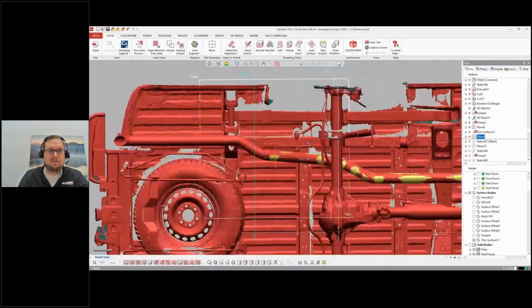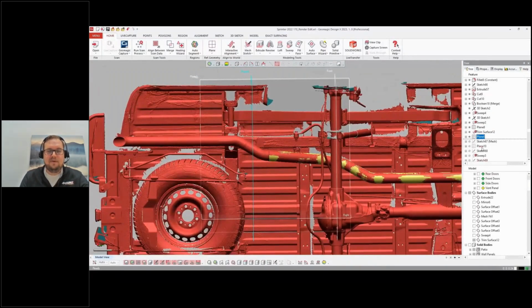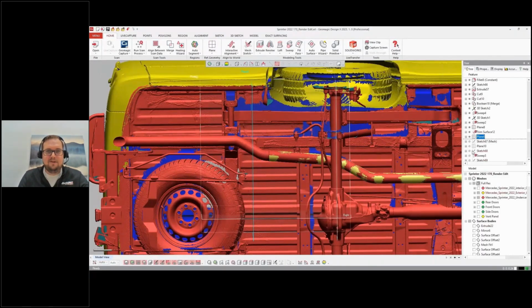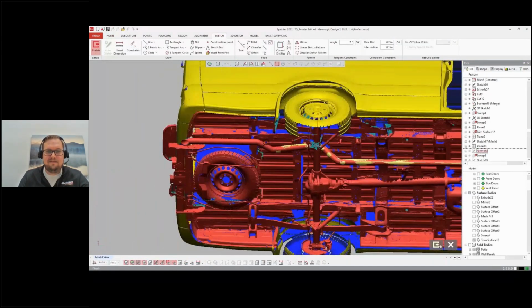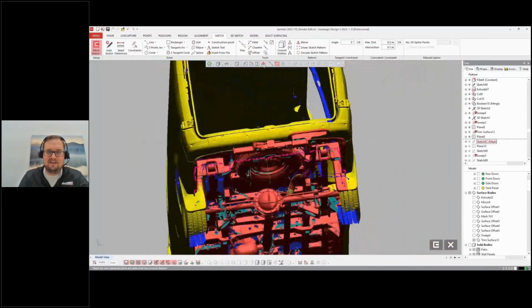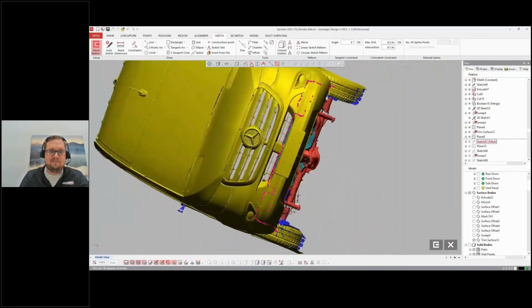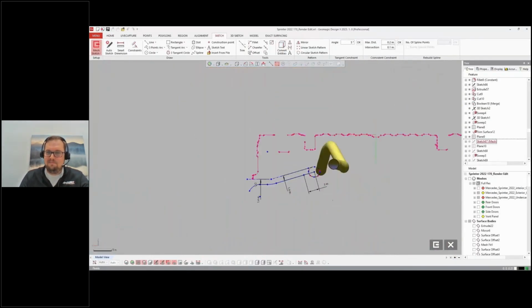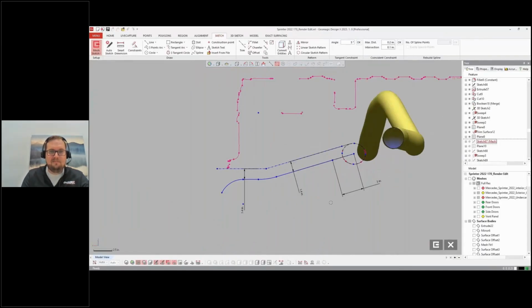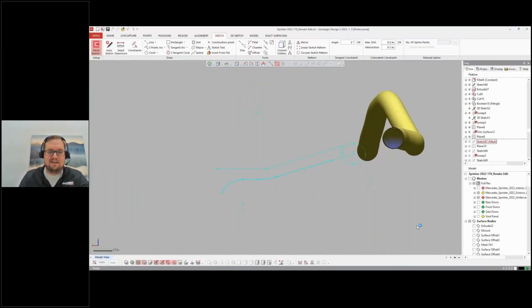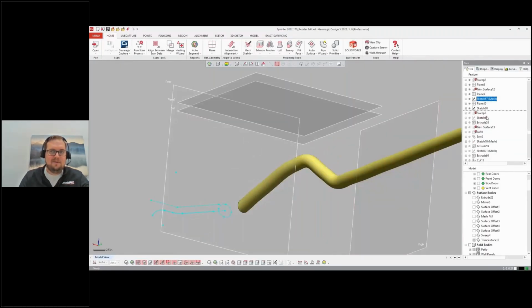And I am going to do a quick sketch on this new plane. And I want this exhaust to exit just after the rear wheel. Now, I did actually look at creating some dragster style exhausts, but I figured that might be a little too high profile. So I'm going to do just a very simple turn down here. So once I have a sweep path and a sketch created for this, I can go ahead and make another CAD surface. So you can see I'm utilizing that mesh sketch to tell me exactly where I need to place this exhaust. So mesh sketch through the undercarriage portion here, and I want to just come below. So I'm giving myself that offset distance of the size of my pipe, and I want to create that sweep.